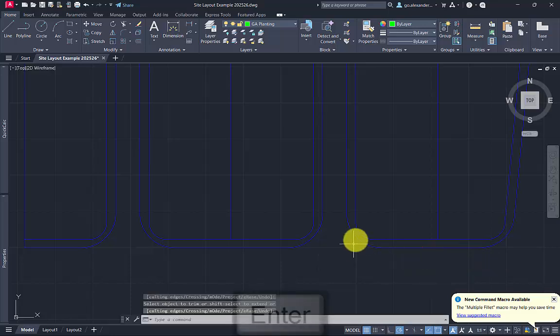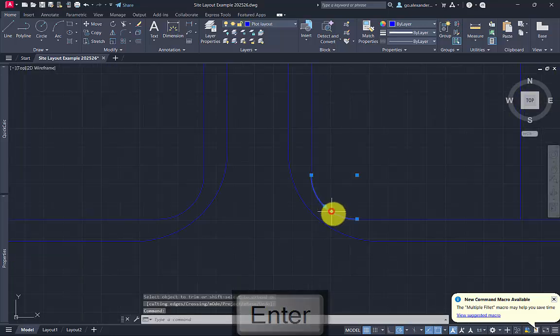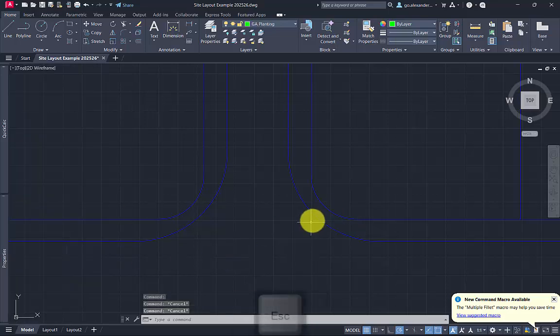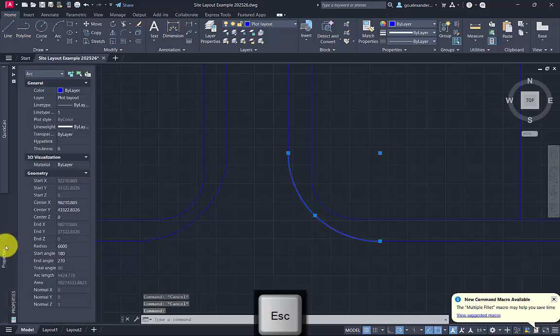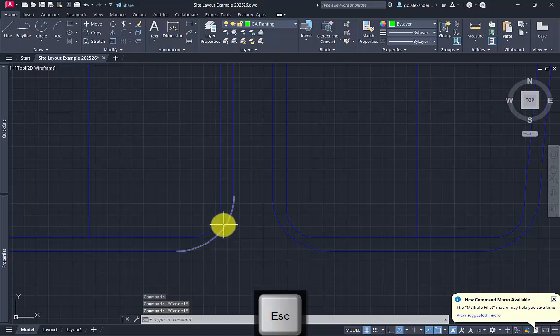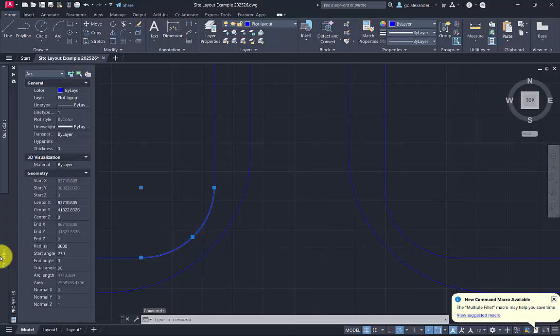Something looks a wee bit off actually in terms of that width. What have I done? Properties, 3000, 6000. Yeah, the footpath thins there, so maybe technically those radiuses should be 2500, should they?